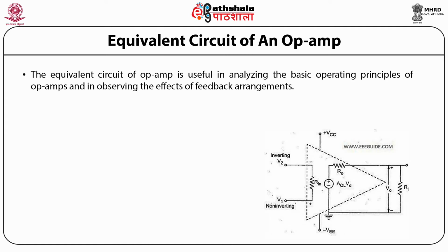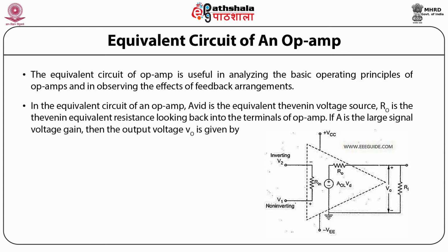The equivalent circuit of op-amp is useful in analyzing the basic operating principles of op-amps and in observing the effects of feedback arrangements. In the equivalent circuit of an op-amp, as shown in the figure, A times VID is the equivalent Thevenin voltage source, R0 is the Thevenin equivalent resistance looking back into the terminals of the op-amp.